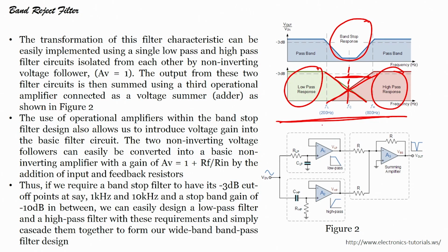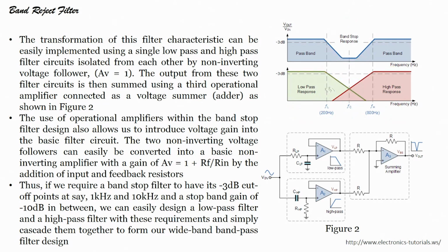I have a low pass active filter, a high pass active filter, and a summing amplifier. We have seen the op amp as a summing amplifier. You see the output voltages fed here, so it is like V1, R1, V2, R2. This output will be minus RF into V1 by R1 plus V2 by R2, which is what we have seen. So that will be my V out.